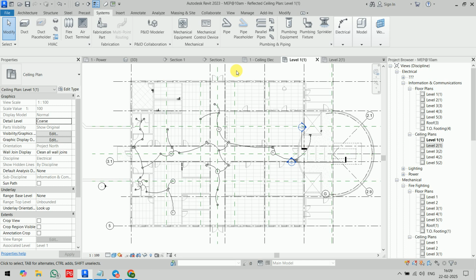I thought, okay, everything we are connecting, so why is it coming like this? I didn't understand back then. So you cannot figure out the number of circuits otherwise. That's why you have to connect individual rooms, so the number of circuits is there accordingly. That's the reason. But for fire alarm you have to connect everything to the FACP. Only that is possible.